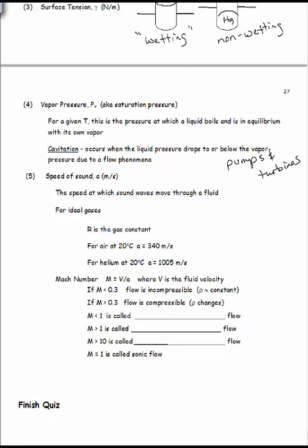And finally, last thing for this chapter is the speed of sound. And we're not really going to do supersonic kind of problems, but what we're going to do is just incompressible problems. Okay, and incompressible is going to be if the Mach number is less than about 0.3, what we can do is assume that rho is about constant and our flow is approximately incompressible, even if it's something like air, as long as the temperature is not changing too much too.